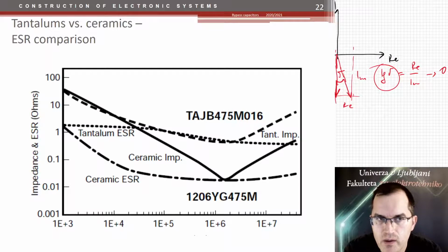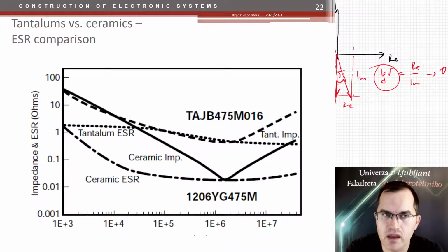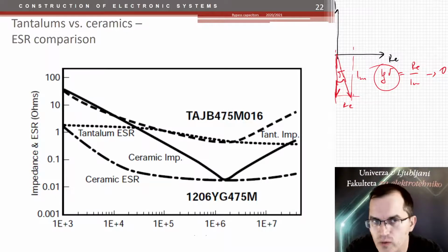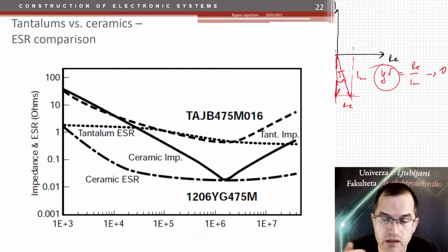Because what you need in your design is of course high quality capacitors in the power supply arrangement, but then you need one capacitor which is not that high quality, which has to have a higher value, but maybe also higher series resistance to make the damping of the resonance circuit. And this could be done by a tantalum or even an electrolytic capacitor in that matter.